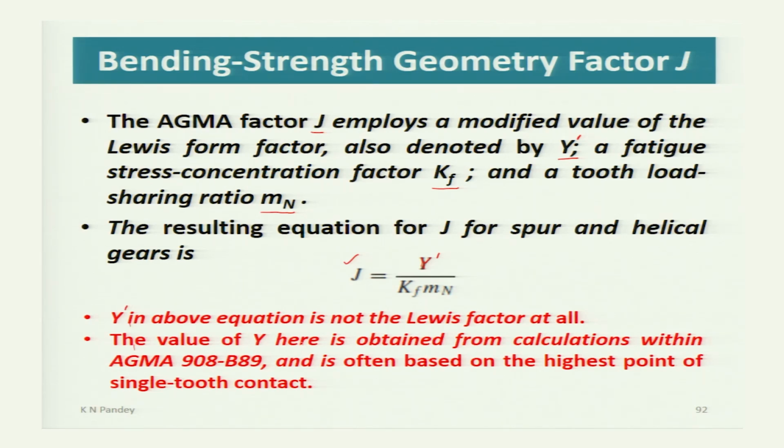The value of Y here is obtained from the calculations within AGMA 908-B89 and is often based on the highest point of single tooth contact, the point where single tooth contact will occur. Because we are saying that due to load sharing, single tooth contact will not occur at the tip, but slightly below the tip.